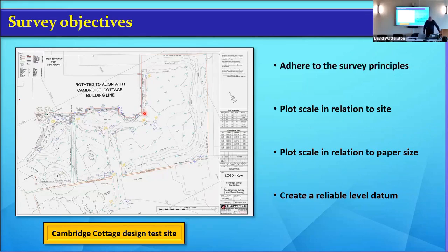So a survey will be collected at what the availability of the resolution or the definition that the particular equipment the surveyor uses will be able to give you. And that is up for debate. So what you're going to ask him is, what sheet size do you want? And what plot scale do you want? And obviously, once you get some experience in it all, you're going to then decide, actually, 1 to 100 scale is fine. Or for doing my preliminary work, 1 to 200 would be fine. But again, what's the point in doing the 200 if it's going to be a tiny sheet? When eventually you're going to use it at 1 to 100, you might as well go for 1 to 100.